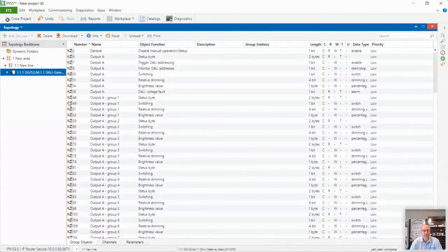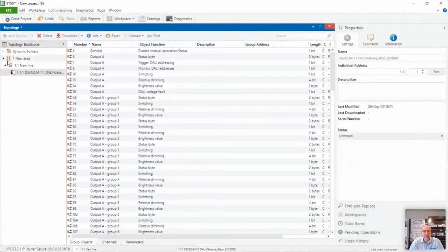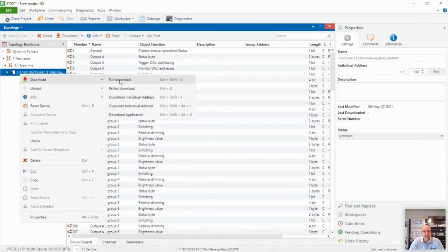If you remember last week, two of the important things we have to do is we have to download the DALI address. So here's what I can do actually, because I have one connected behind me. The first thing I'm going to do is give it an address. I know the one I have is 120. Let me change it to 130. So my device address is now 130.